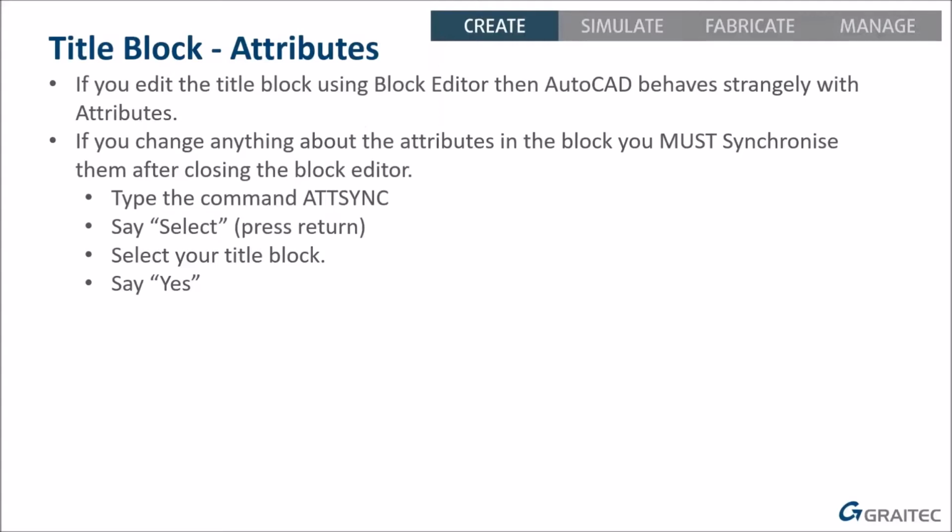And this is something that people don't really understand and don't realize. Everybody I know always explodes the block, purges the file, creates a new block, and then has to go through all getting everything just right again. But you can edit them just doing the block editor like I've shown you, as long as you remember to synchronize the attributes. And that means you have to type in this command, ATTSYNC.